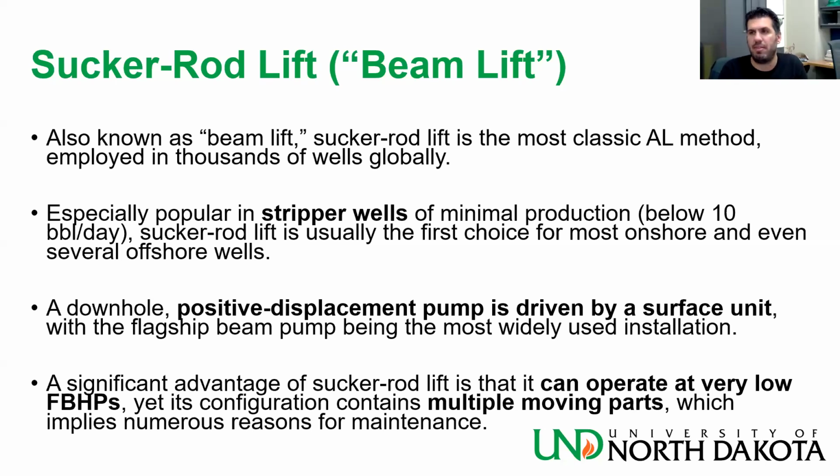But if we want to replace something downhole, we need to bring a workover rig. We need to retrieve the downhole pump, find what is wrong with it, and fix it. It is not an easy process. The workover rig, we call it the gorilla in the room. If the fixing involves bringing a workover rig on site, automatically it is the critical point between the bill that you have to pay being huge or something very small. There is no in between. Once you need the workover rig there, you are in a tough situation.